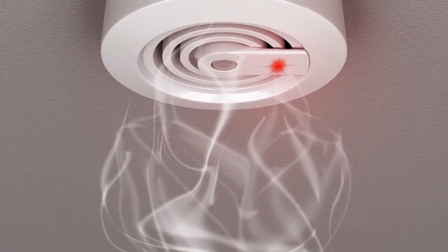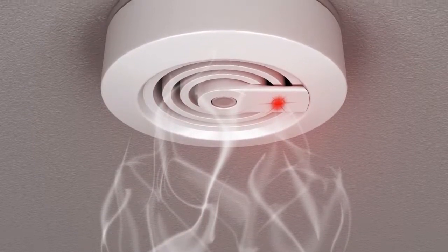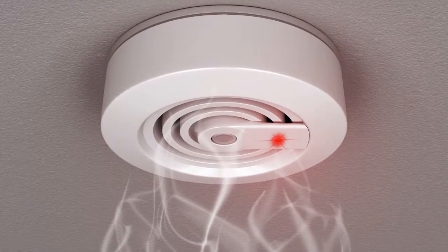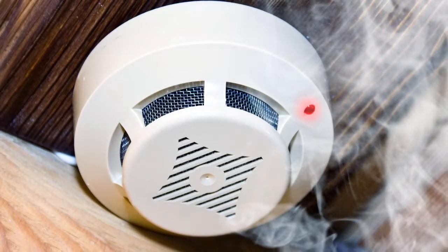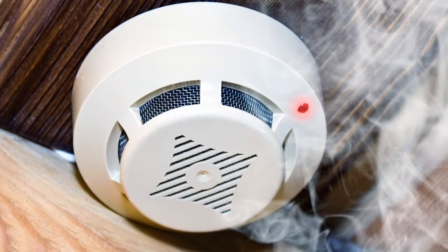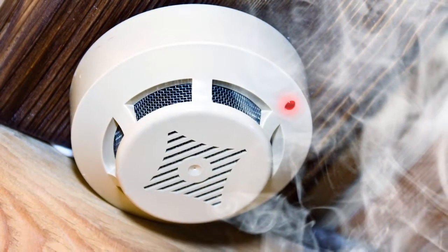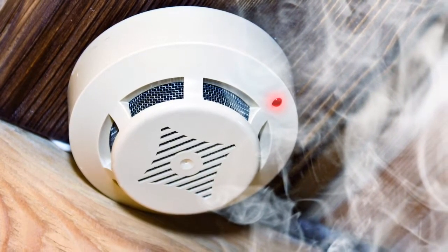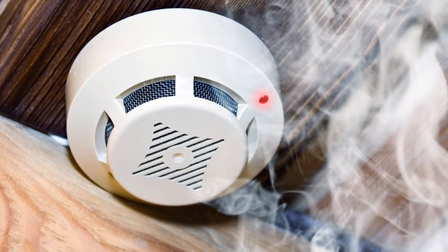What is actually happening in photoelectric fire alarms is the LED sends a beam of light, usually down a T-shaped chamber. Sitting at the bottom of the T is the photocell. When smoke enters the chamber, some of the light is scattered by the particles, with some rays getting sent down to the photocell. When this photocell detects light, it generates an electrical current that triggers the alarm at a certain threshold. Once that current stops, the smoke is cleared, the alarm will stop. Photoelectric detectors are better at detecting slow smoldering.